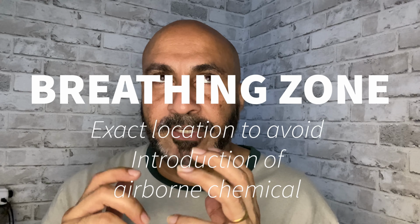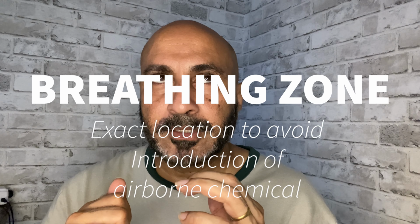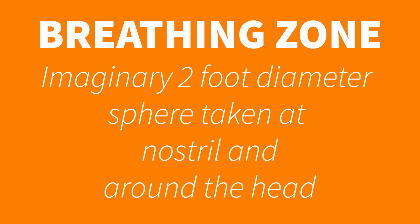Now the fundamental of exposure control of airborne contaminant is we want to ensure that the suspended airborne contaminant doesn't get into this breathing zone, the 2 feet sphere. You see, 2 feet diameter, not radius, a 2 feet diameter sphere. We don't want the suspension of that airborne contaminant to get into that. So when you have that in place, how do you use general ventilation? How do you use general ventilation?